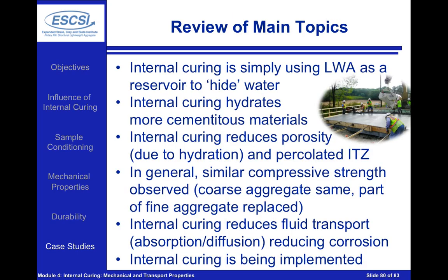So what I really want to do now is try to wrap up and highlight the main topics that we've covered throughout Module 4 here. And what we've focused on is the fact that internal curing is the use of lightweight aggregate. Typically it's going to be the fine lightweight aggregate that replaces a portion of the sand, and this will act as a reservoir to hide water inside of our concrete.